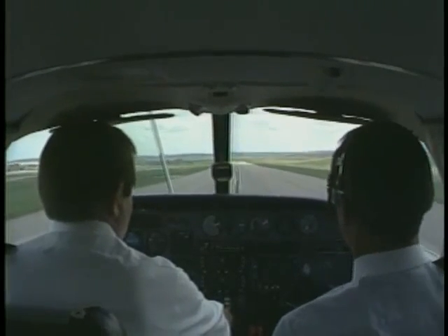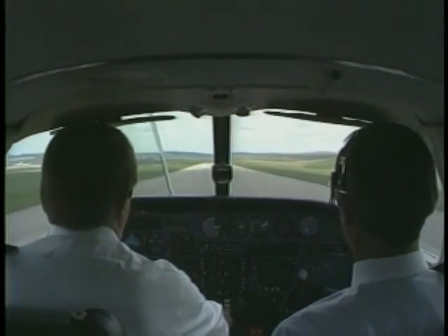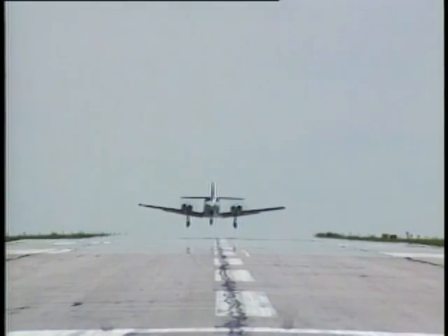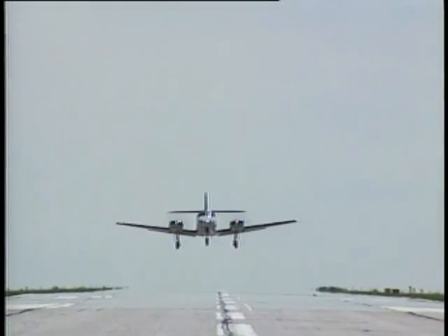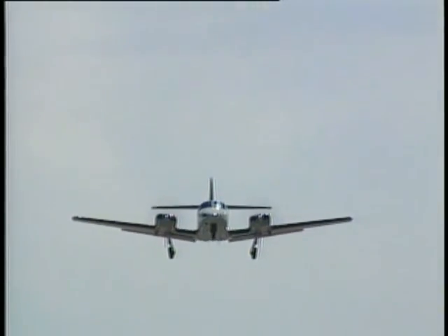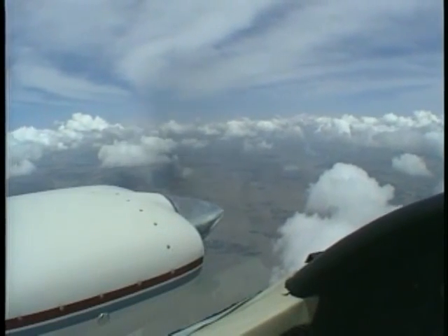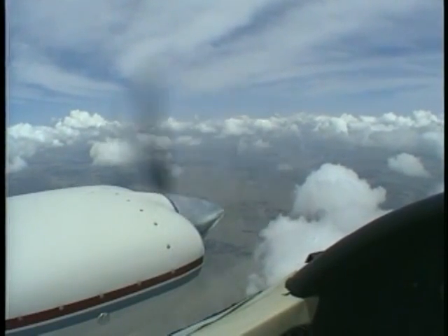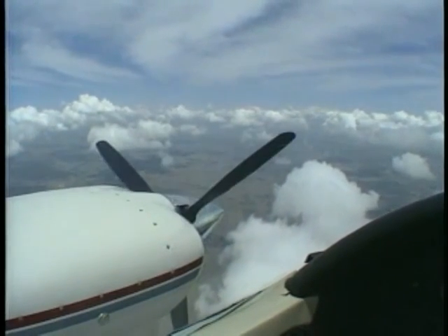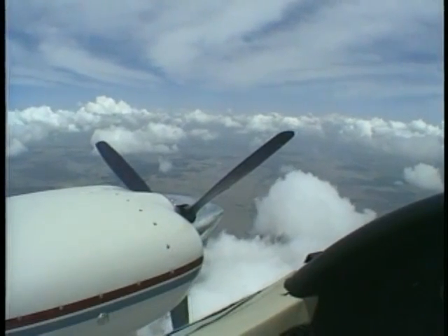According to FAR 61.195, you must hold a multi-engine class rating on your pilot and flight instructor certificate, and have at least 5 hours of experience as pilot in command in the make and model of multi-engine airplane before providing this instruction. The multi-engine checkout may include a review of the pilot's general knowledge of systems and aerodynamics, but many of the subjects to cover will be specific to multi-engine airplanes.